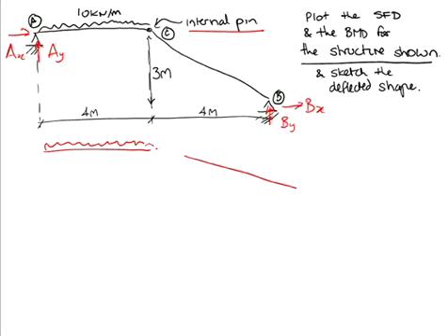AC or CB? Yeah, I'd give AC a go. It's horizontal. We have a load, 10 kilonewtons per metre. Our member is 4 metres long. So tell me, what are these 2 reactions equal to? Some symmetrical loading, symmetrical structure. Each of these reactions here is equal to 20 kilonewton. So I have an up force 20 there, a down force 20 here, and thus over here, what's my up force? 20. So we've now solved for 2 of our reactions, our vertical reactions.